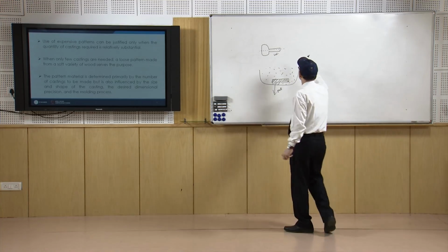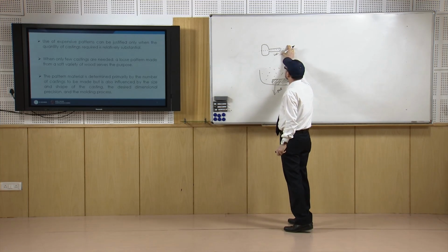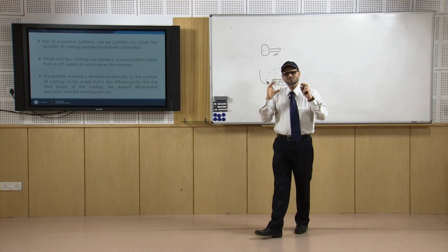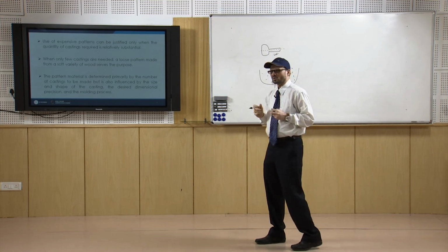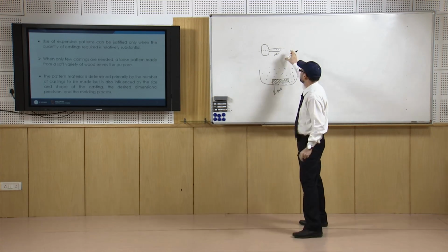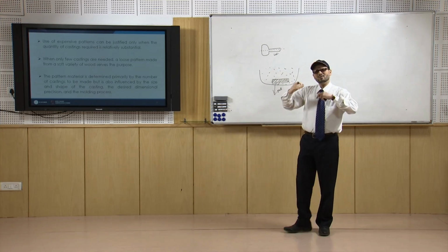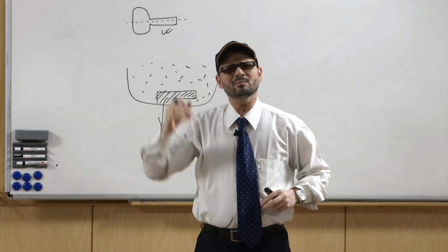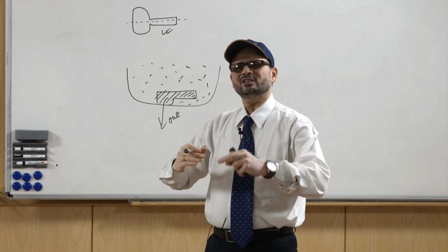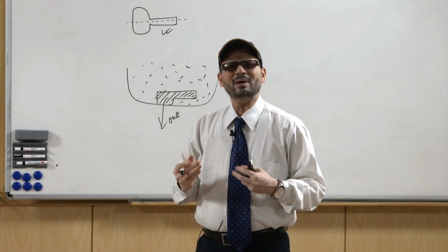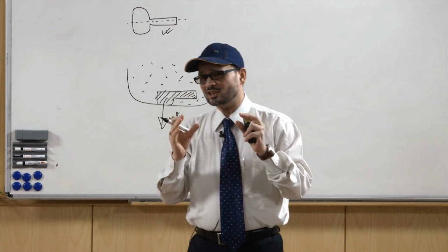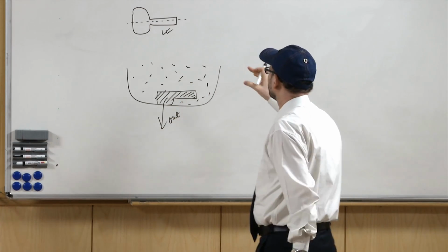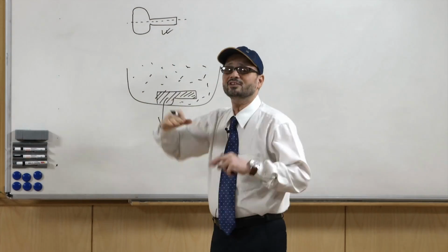If you have to use it only a single time, you can think of a pattern material which should be cheap, because you are using it only once. But when you are going to use it a larger number of times, there is deterioration in the quality of the pattern, or a decrease in the accuracy of the dimensions, because there will be wear and tear.